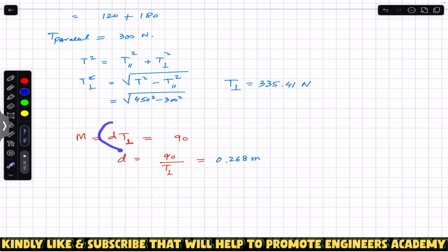The scalar definition of the moment is always the perpendicular distance multiplied by the force, d times F. As we know that the moment is always r cross F, we can say rF sine of theta, and r sine of theta is the perpendicular distance. So we can say that this is d perpendicular multiplied by that force F, which is going to produce the moment about a given axis.